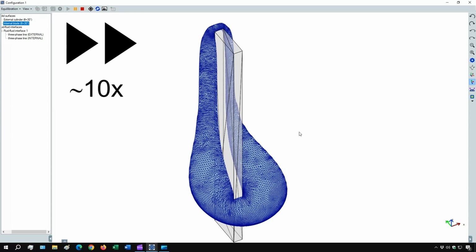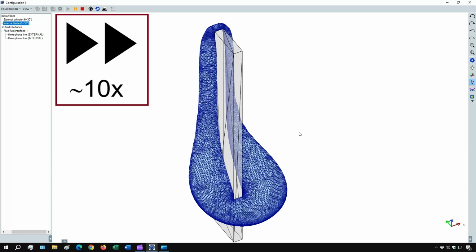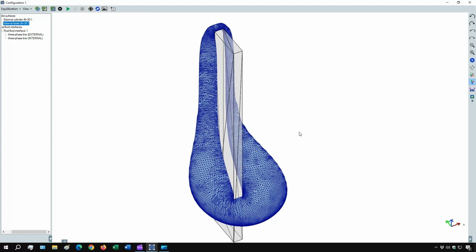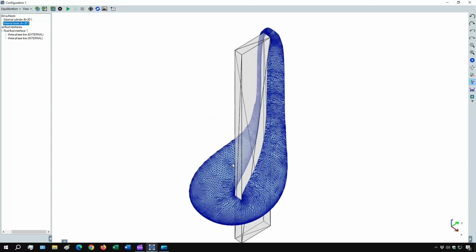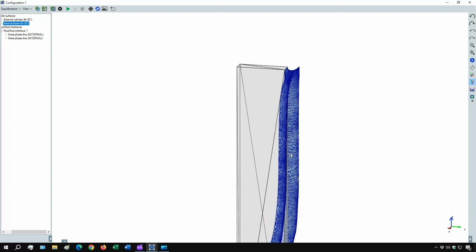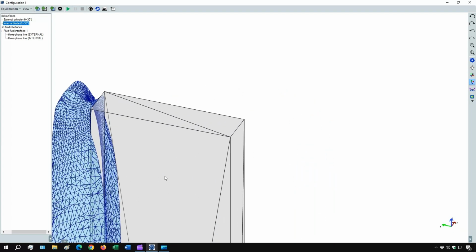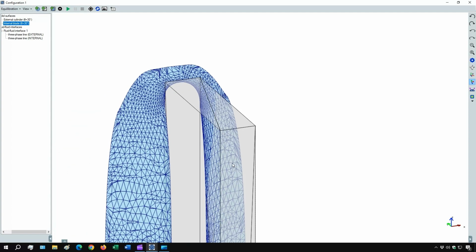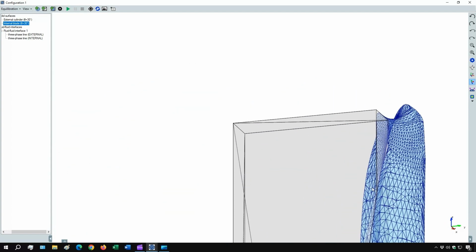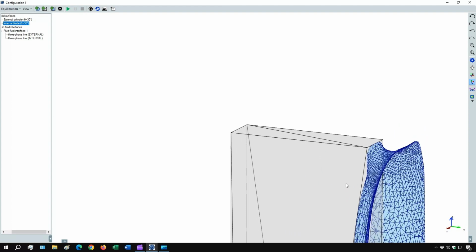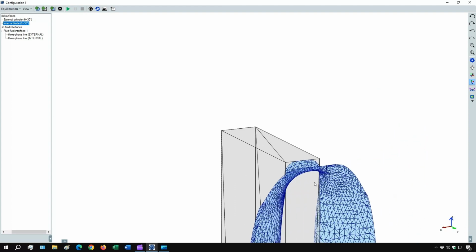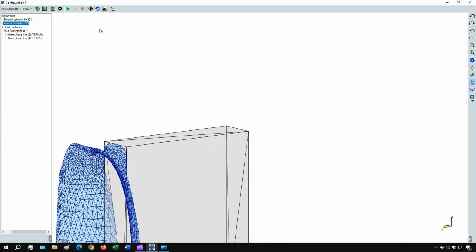So, to sum up the advice that I just illustrated to you: when the initial shape of the fluid interface mesh is far from the equilibrium shape, and when the equilibrium shape is not trivial, for example, because the three-phase contact line is very long, as in this case, then it is recommended to launch the equilibration, selecting a not too high degree of refinement for the mesh. Then, once the equilibrium shape has been computed for the not too refined mesh, you can launch a new equilibration to further refine the mesh, if desired.